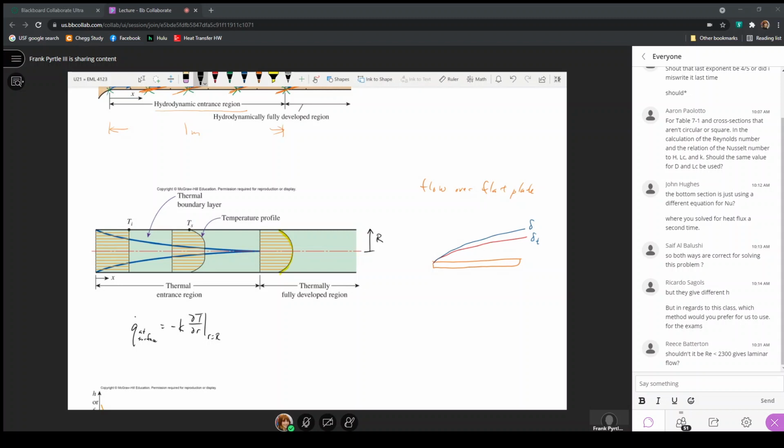These orange lines are indications of magnitude of the temperature. So here, actually in this particular problem, the way that this is drawn, the highest temperature is along the center line. So it says that the heat transfer is actually from the fluid into the surface, because here is the temperature of the surface, and here's the temperature of the fluid. And if we're moving from left to right, according to the length of these lines, the highest temperatures are along the center line, the lowest temperatures at the surface.